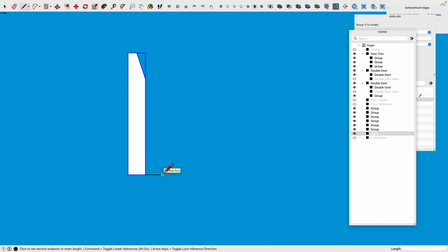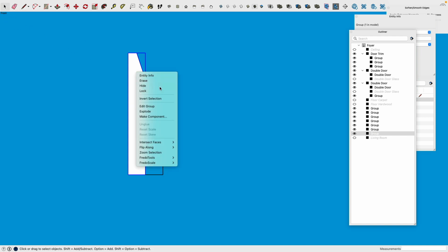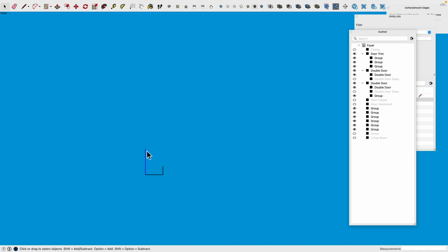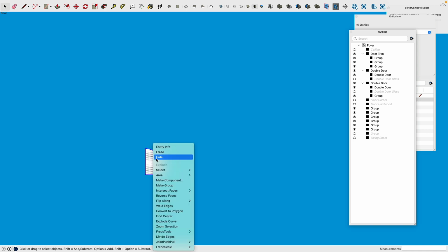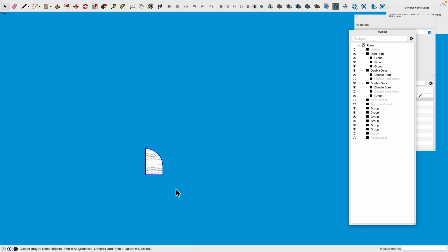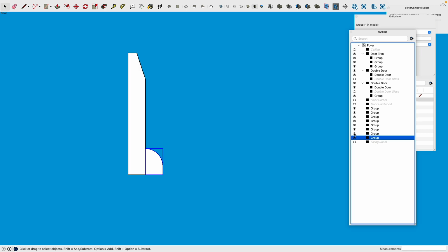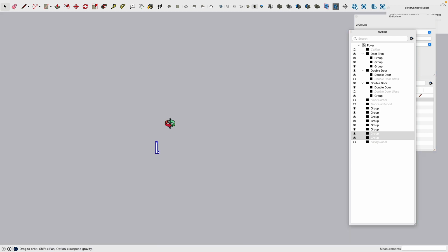So here this goes 0.25 up. That sounds confusing. Here, let me show you why. So you see start point and end point of the arc. There's our arc from there to there. And move this till it says tangent and vertex. Click. Beautiful. There we are. Triple click and then make group. Cool. Okay. So then this way you can create these two pieces.